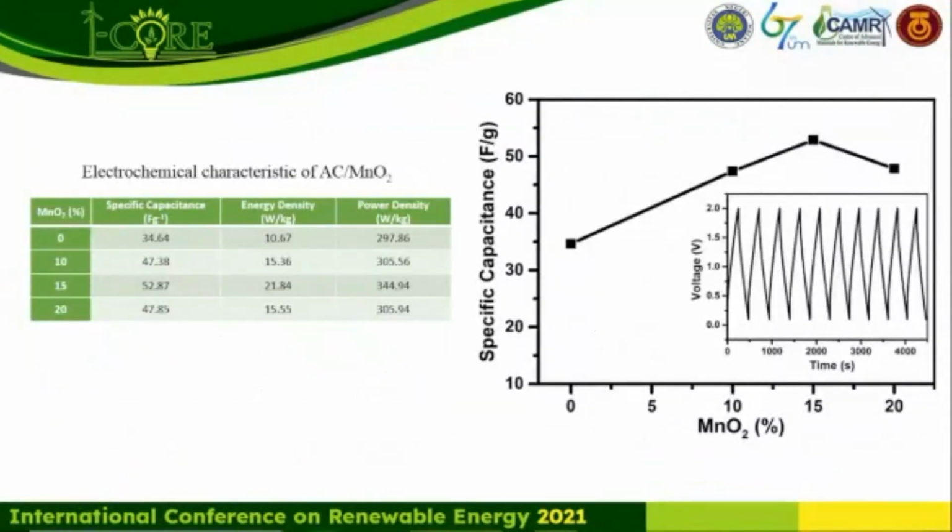This charge-discharge measurement uses a current collector, such as aluminum foil, with a voltage range of 2.5 until 2.8. The capacitance depends on the current density, potential window, and discharge time. The capacitance can be classified according to the charge storage capability of the active electrode materials or devices. In this study, we used gravimetric capacitance in farads per gram.